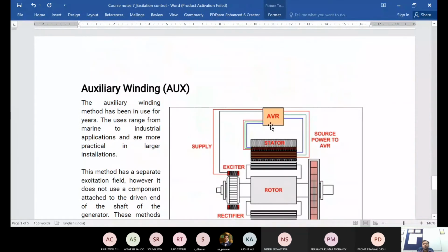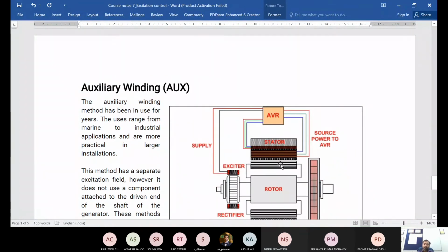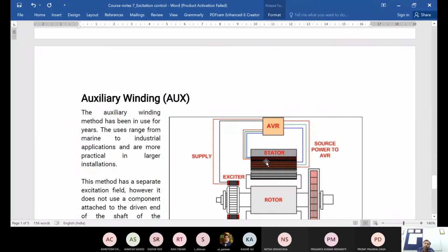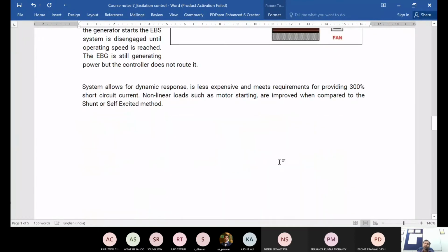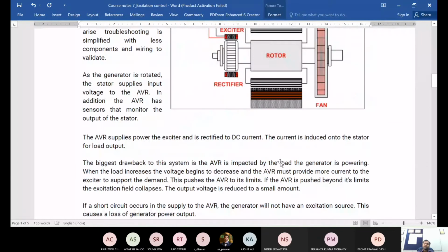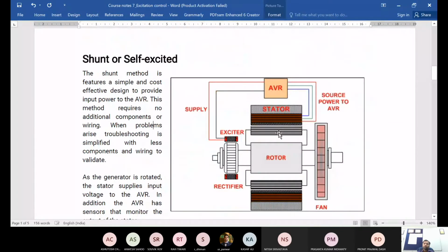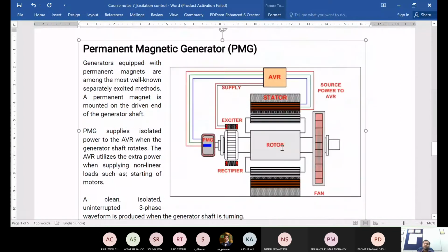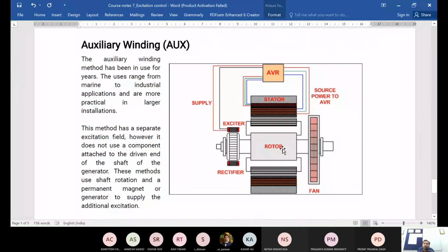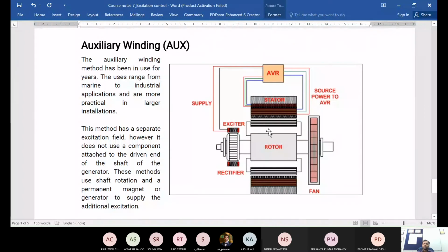Yeah, right, this one. So even if you look at the stator here, the cross section of the stator, interestingly, you will find there is this extra layer which has been shown here for representation purposes. If you see here the stator, you have this type of representation, 3 layers primarily. And if you look at this one, there is one extra layer in between, this brown one. These stripes were there in the first one also, and then this dotted portion. But there is this extra brown layer here, which is basically one additional auxiliary winding. So this auxiliary winding is one additional winding which is coming up here.